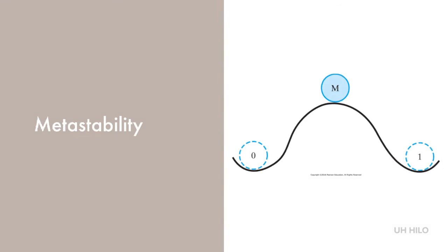It's fairly unlikely, but this can happen. If it happens for an entire clock period, then things can go very bad. The authors discuss an experiment where this happened at Washington University in St. Louis. We can never eliminate this problem totally, but having a series of synchronizing flip-flops helps to reduce its probability.